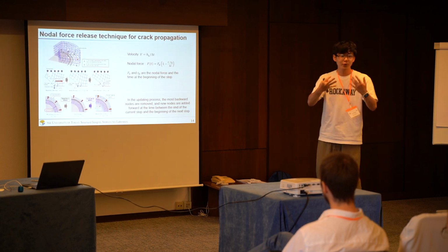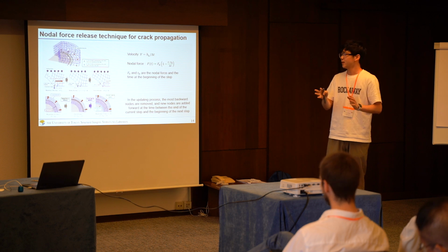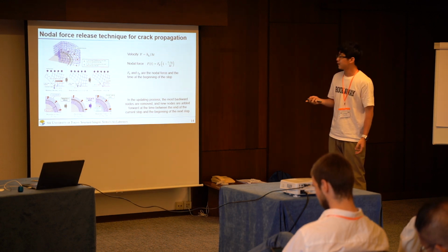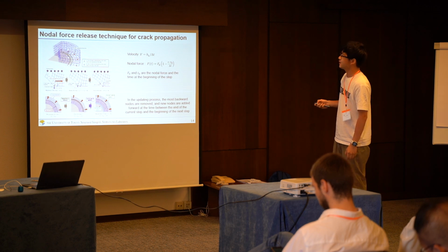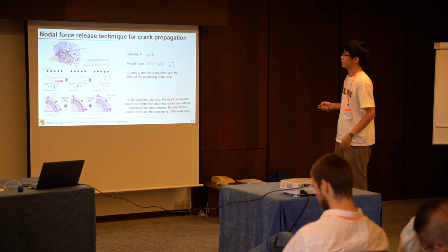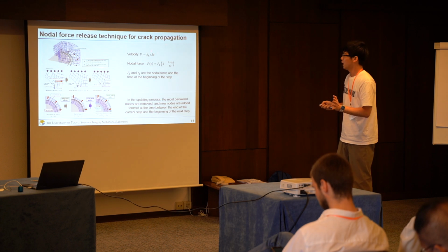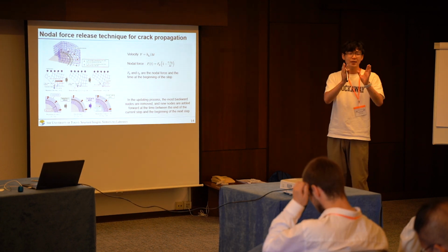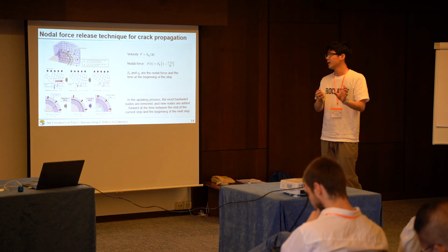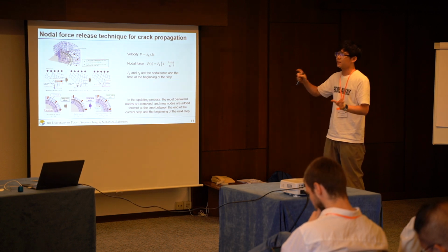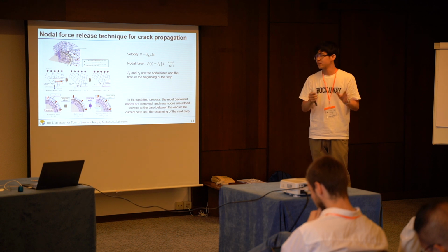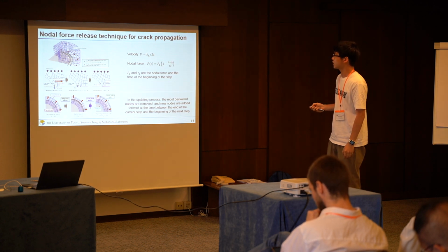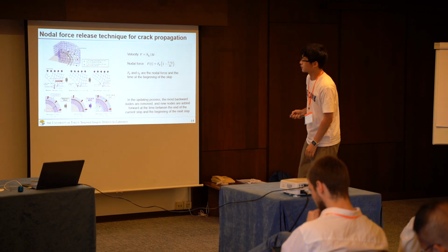Because we need to simulate the crack propagation, we introduced the nodal force release technique. In this technique, the velocity of crack propagation can be expressed using this simple expression. Here, HL is the length of each local element, and delta T is the time increment of each step. And for the nodal force, we use this expression, and you can see this figure.